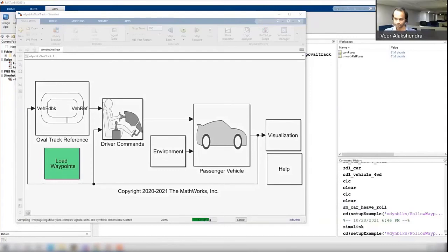Meanwhile, it is running. There's a nice question again: is it useful for robotics design? See, not exactly this. This is very high fidelity, and in robotics we don't move the vehicle at very high velocity, so we are not concerned about the tire effects and all. Rather, you can use the Robotics System Toolbox where we have provided a simple bicycle model. However, from here, if you want, you can use the 3DOF single track block model.